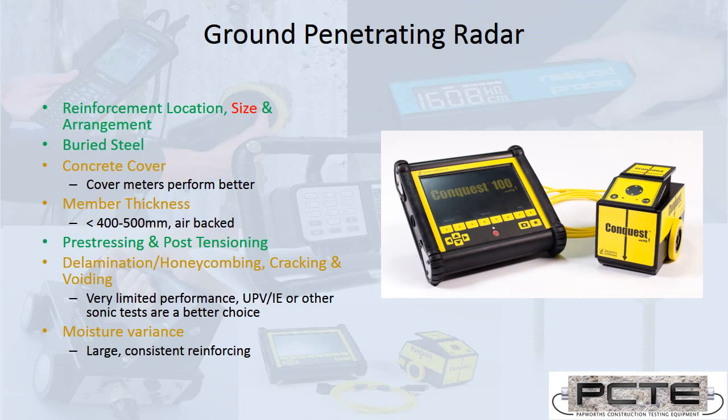But very small voiding, tight cracking that doesn't separate a great deal, are not going to be directly visible as signals on the scan. They may have some effect upon signal strength, which I'll show you in a second, because that is a technique used to evaluate bridge decks, but it's not as simple as working with basic GPR data.